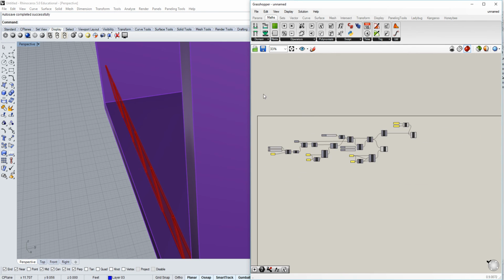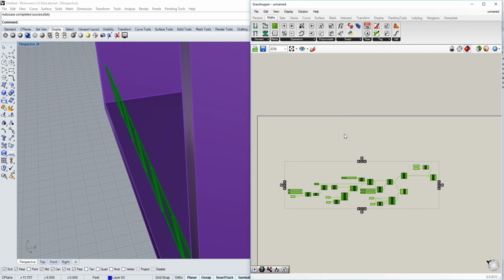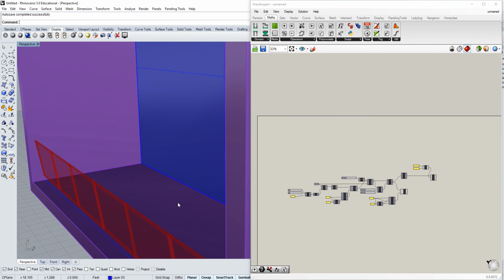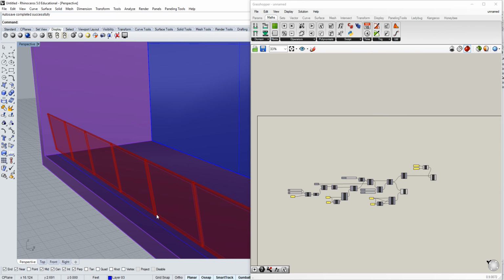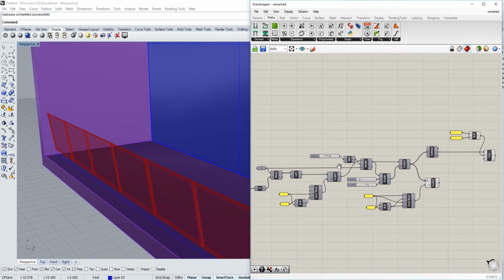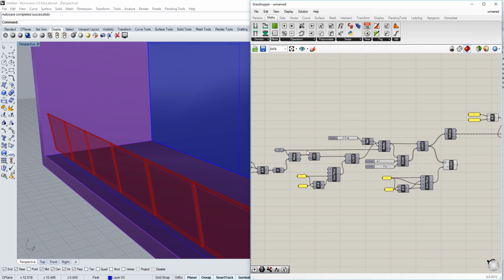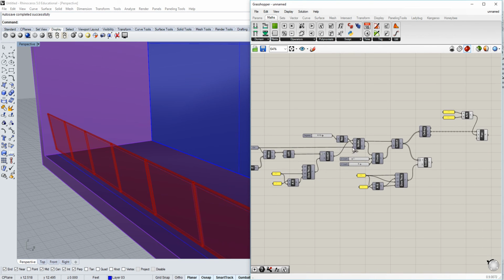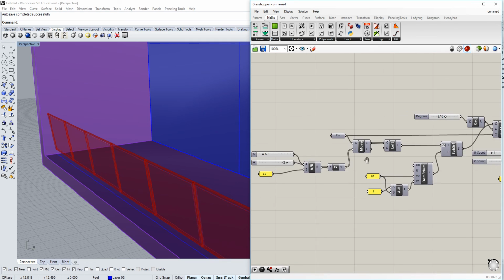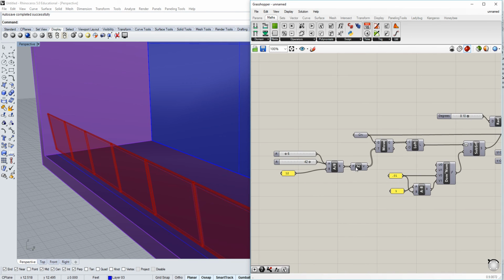So going back from our overall full definition, we need to find the spot that we can create a handrail that's going to be exactly vertical from my bottom rail. So it's going to sit 36 inches above the ground along the edge here. And so to do that, I'm actually going to use the curve that I offset. Let's see here. There we go, 6 inches.